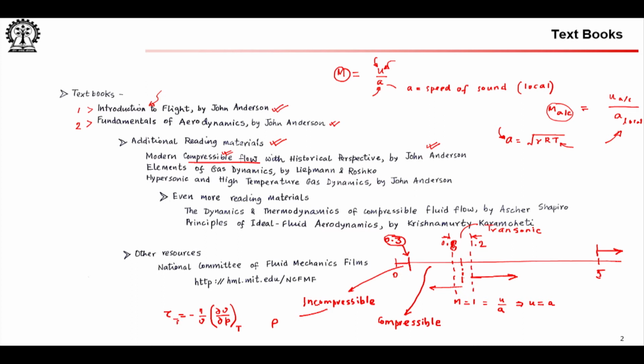And of course, we will see that when you calculate compressibility, it depends on the method in which you measure it. So, here my subscript T stands for isothermal. So, you have a vessel where you are maintaining the temperature constant, and then you are increasing the pressure on the vessel, and you are trying to see what is the fractional change in specific volume. That will give you a measure of the compressibility of that particular gas, and that will be called isothermal compressibility.